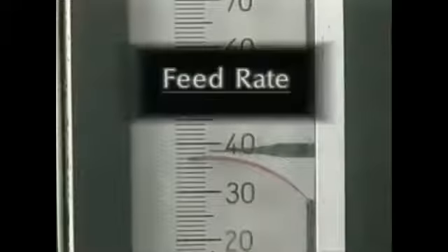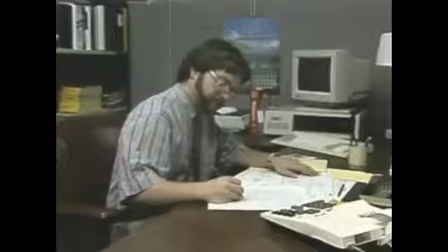The feed rate is the rate at which feed mixture is pumped to a column. The flow of feed to a column can affect the quantity and quality of overhead product and bottoms product. For that reason, an optimum feed rate is normally determined mathematically based on system equipment and the materials being processed. An optimum feed rate is often determined when a system is designed and may be modified according to the mixture being distilled. However, a range within which the system functions efficiently is usually specified as well.